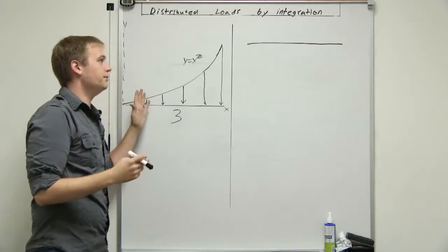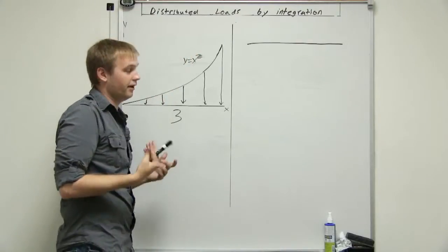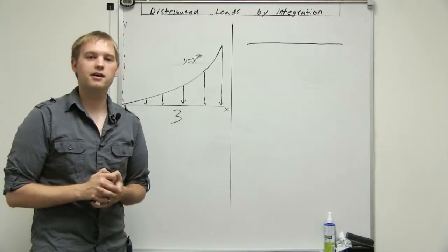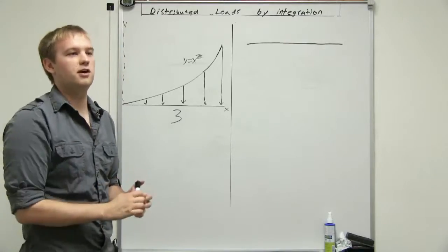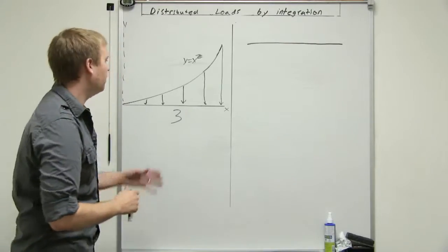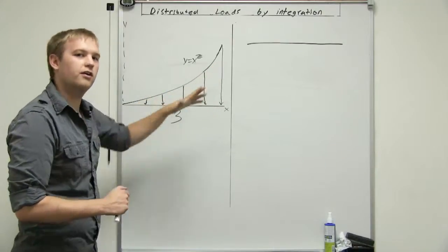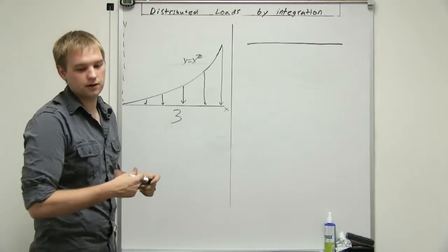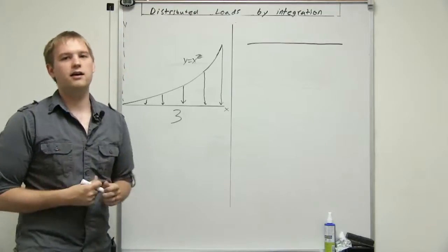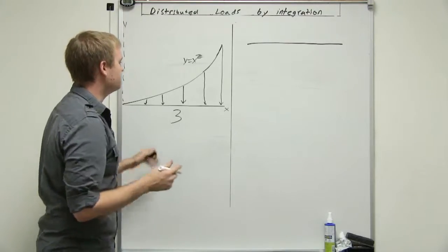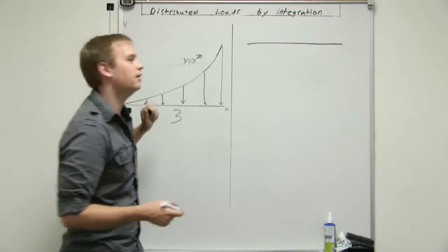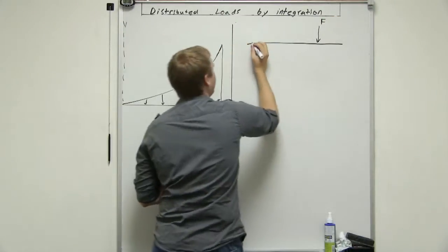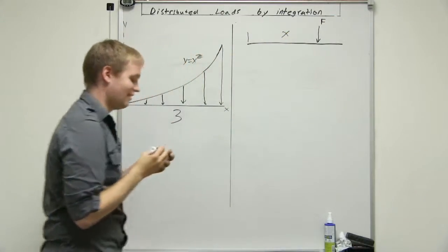So the way that we do this, you already could have guessed, is by integration. If we go back to the last video when I was talking about how you can think of this just as geometry and finding the area of an object, well, how do we find the area under a curve? Well, that's by integration. So that's exactly what we're going to be doing here, except we're not really finding area, we're finding forces. So we're going to replace this distributed load with one force acting at a certain distance. We don't know what that distance is yet.